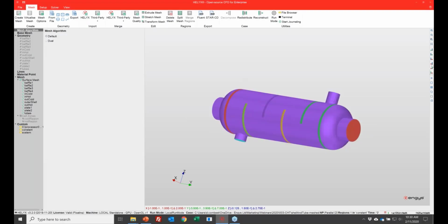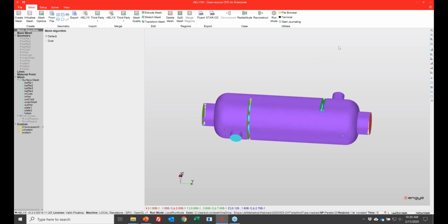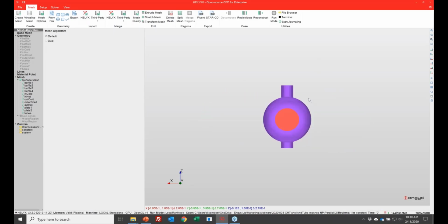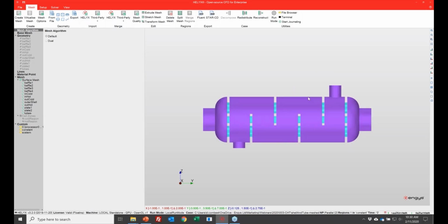Okay, so here, if I want to, I can press 5. Whoops, wait, let's try another perspective. There we go, that was a 4. And then turn on and off the parallel projections just so I can get a side view. So right here, this missing solid, these were the cap plates at the end. I didn't want to model the heat transfer or the heat transport within that. This is where the different baffles are.